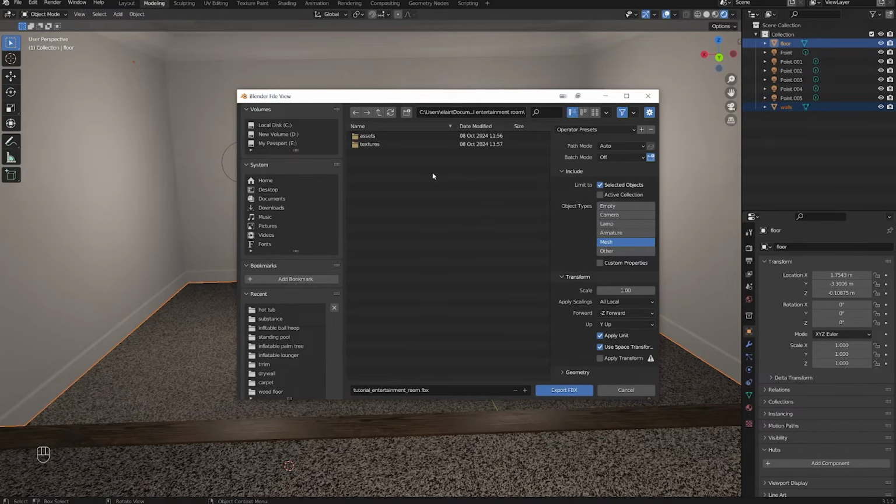One thing to note about Blender versus Unity is objects in Blender have a different scale property than Unity does. So you've got this apply transform here. If you're a beginner, this may not make a lot of sense, but if you click apply transform, it means the objects that are in Blender will be scaled to 1 in Unity. If you don't hit this, it means things will be, I think, rotated at 90 degrees and scaled to 100 because it just comes into the program a little bit differently.